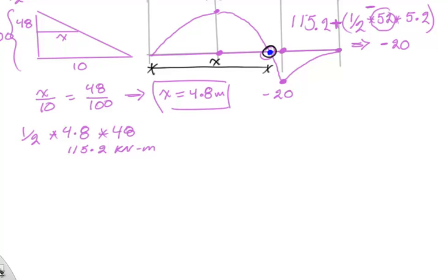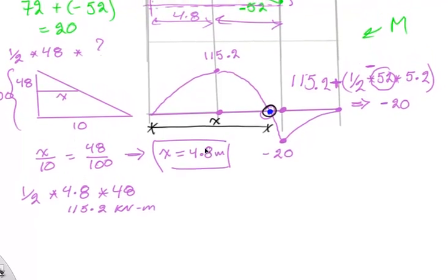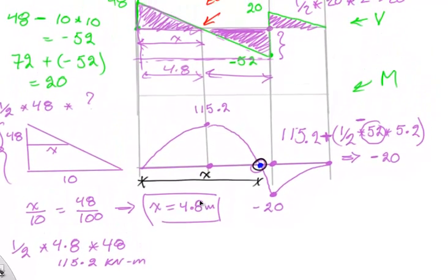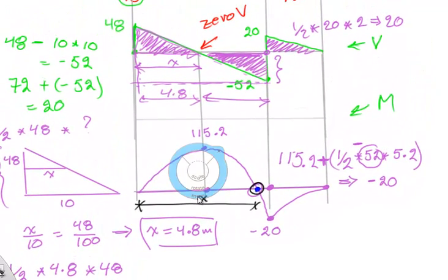And from before we've seen, I'm sorry, let me get this graph again. And from the shear diagram, we've seen that the maximum moment corresponds to the 0 shear. So if I have a positive here and I calculate the area, I'll get the maximum value.